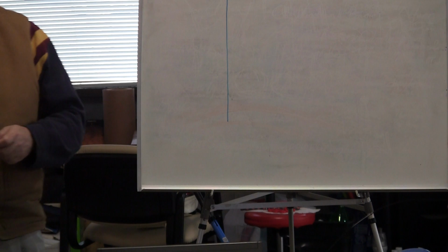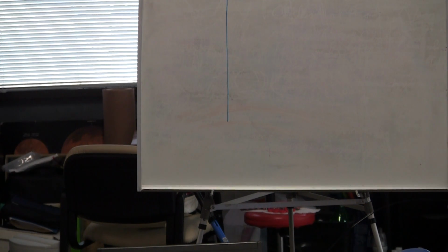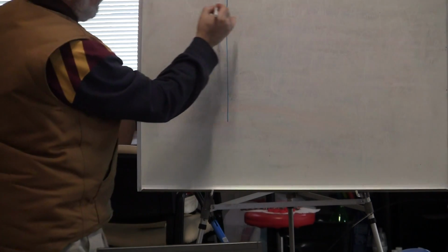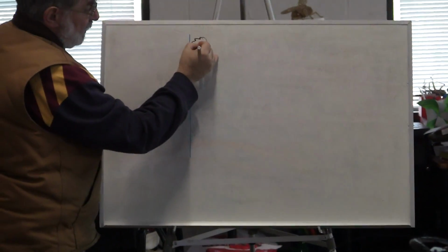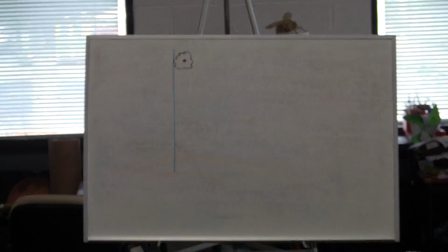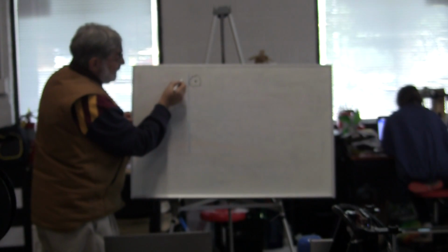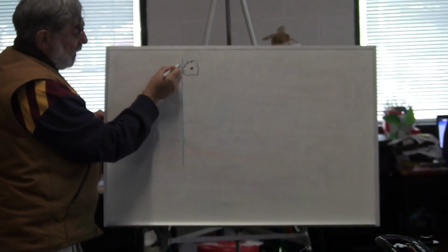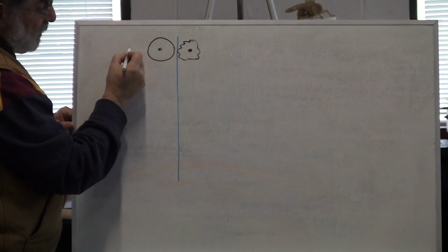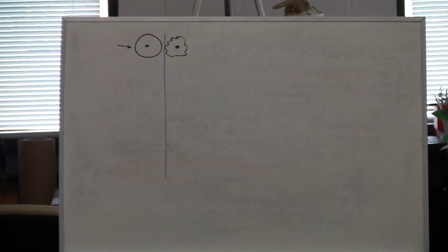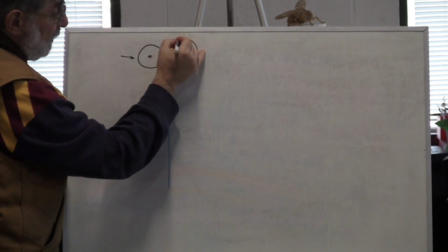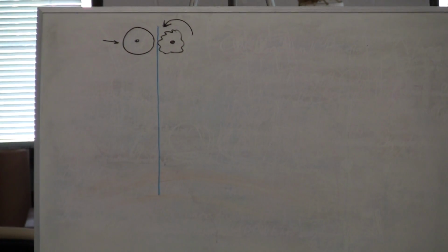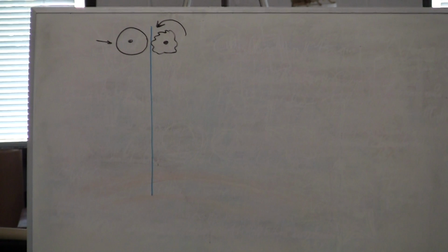Okay. I'm going to go top to bottom. The first thing that happens is a drive. Someplace over here is a gear-looking thing, more round than this. Okay? And typically, although not always, a round bearing that's pressed against it with a spring. And this gear-looking thing spins in this direction to push the filament down. Make sense?